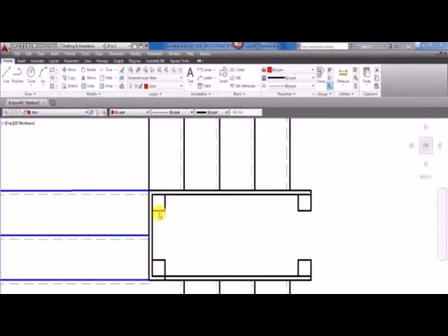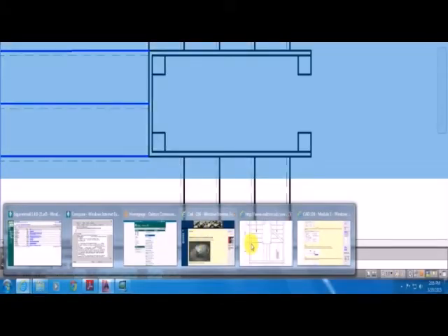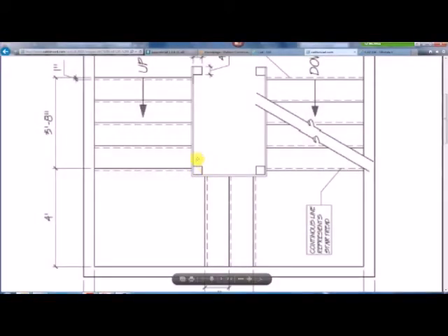So we have one little thing here that we want to fix. If we look at the drawing, and I'm just going to trim this here before I do. It shows that these posts are kind of embedded into the stair detail. So what I'm going to do is I'm going to move them in 3 inches.